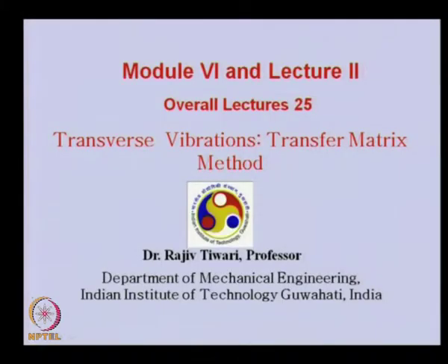Today we will study transverse vibration using the transfer matrix method. This particular method we studied earlier for the torsional vibration case. We have seen the advantage of this method, that it can be applied to a multi-rotor system, and that once we develop the point matrix and field matrix for the disc and the shaft, we can use this for larger systems also.